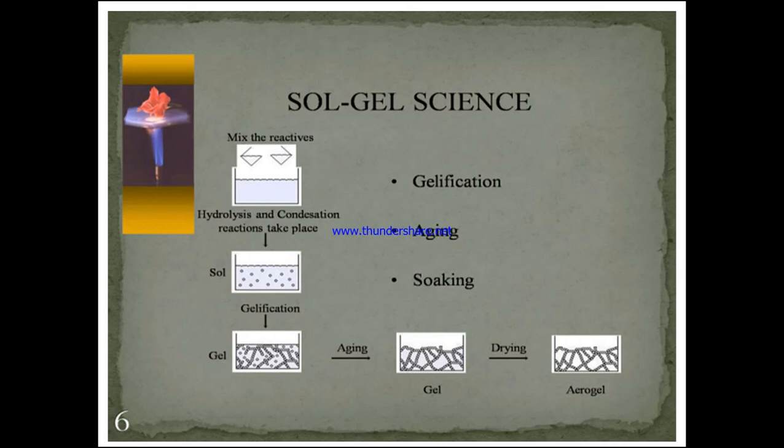So we have to eliminate the alcohol content, then we can extract the nanoparticles. The gel has to be dried. Drying is done by three techniques: the supercritical condition, thermal evaporation and calcination. In most cases we prefer the calcination technique here.